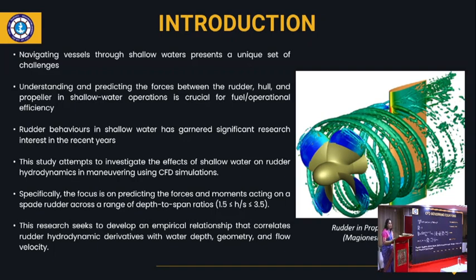This gives rise to an additional term called Reynolds stresses, and for closing this, we go for a turbulence model. The turbulence model we use here is an explicit algebraic stress model, which is quite powerful in predicting problems with medium to high turbulence within the scope of the runs.